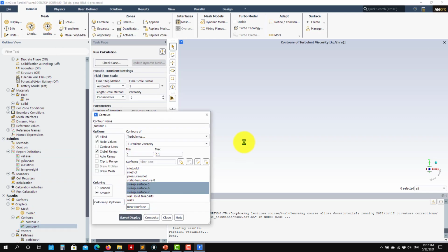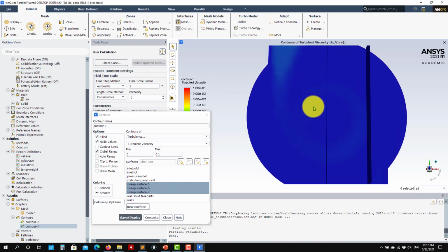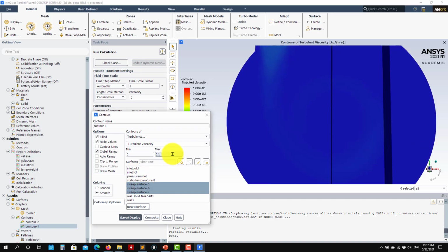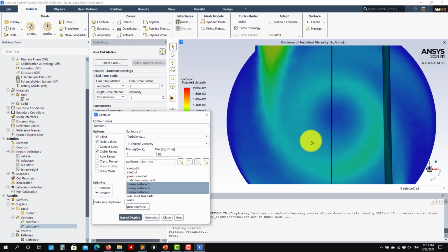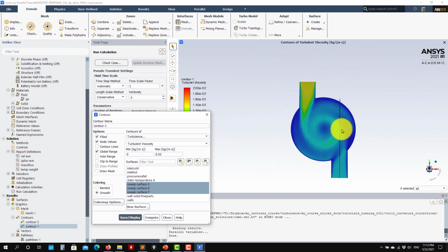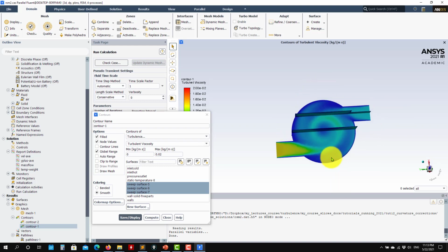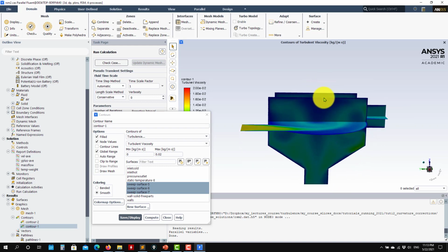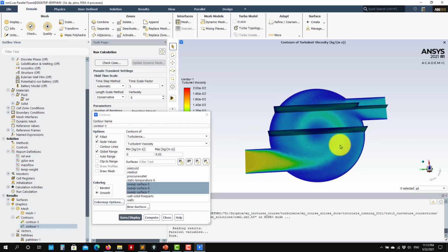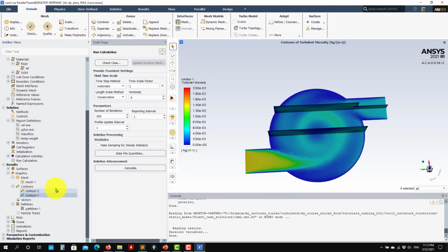So just to take a look at a solution, see that in the same planes the turbulent viscosity values are very low. So let's adjust the scales and see what we have, okay? So it's something very nice. See that it's only adding turbulent viscosity where you have high strain rates, where you have a strong spin tensor. So this is the idea of these models, and these are situations where this model performs very well.